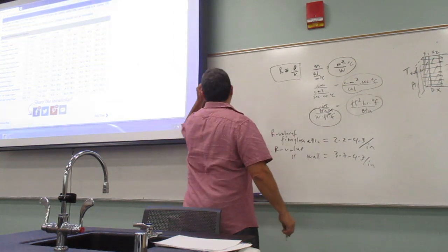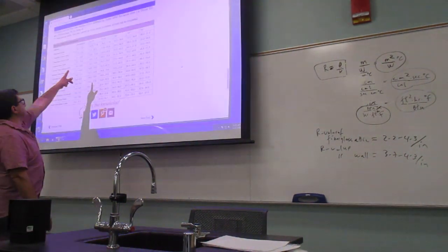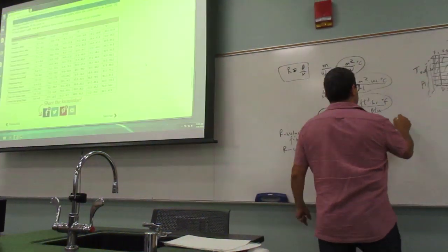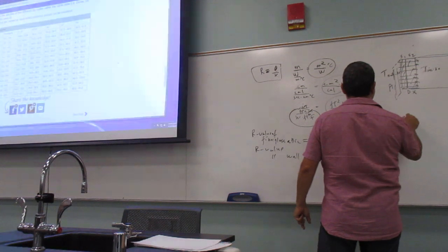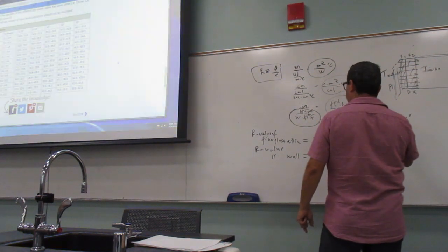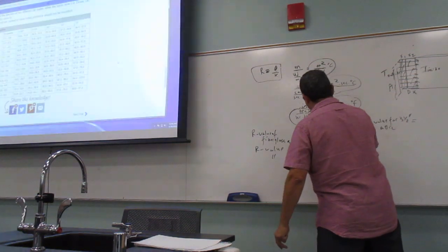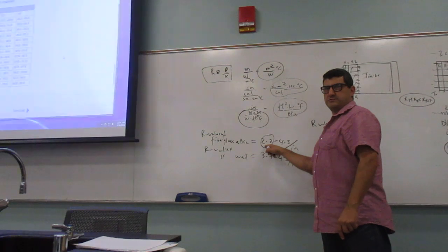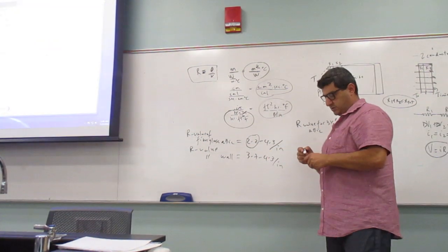So depending on what the thickness is, let's say you put 3.5 inch thickness of fiberglass. What would that be, R value for a 3.5 inch for the attic? Well, let's say you're using 2.2, then you multiply 3.5 inches by 2.2, because this is per inch of the material, right?